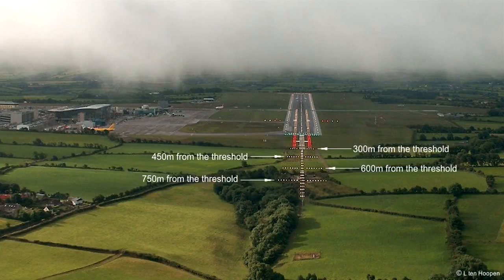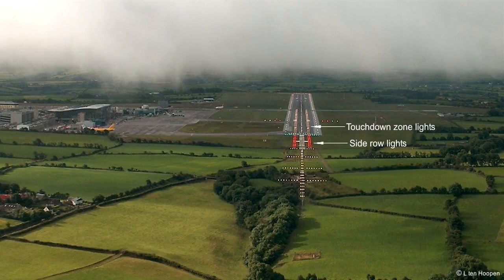The lights forming the centerline shall be placed at intervals of 30 meters from the threshold, and the crossbars shall be positioned at 300, 450, 600 and 750 meters from the threshold. The side row lights will be barrettes of comparable intensity to the surrounding white lights and show red light. They will be equal in length to the touchdown barrettes.